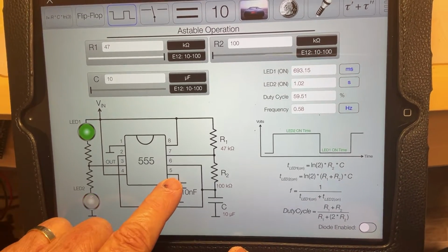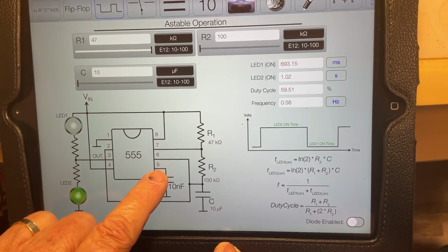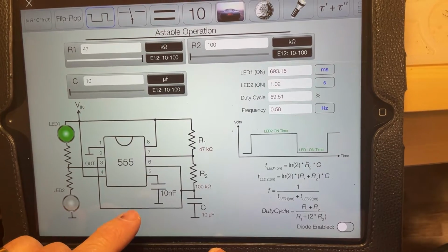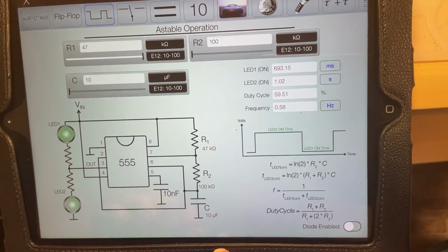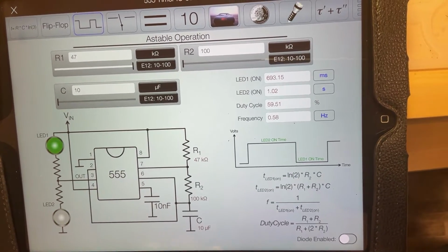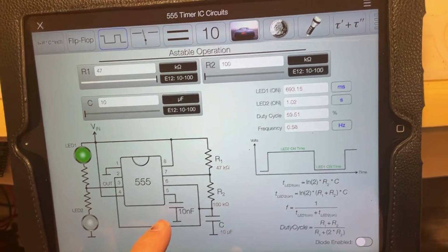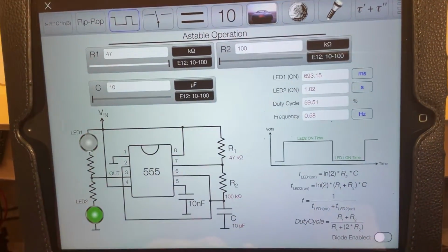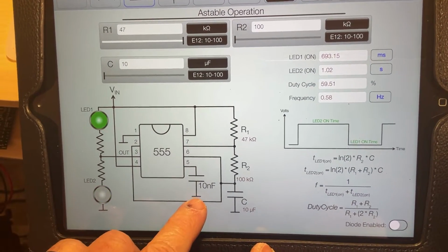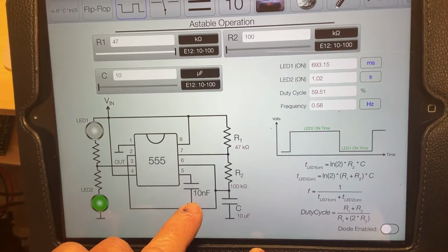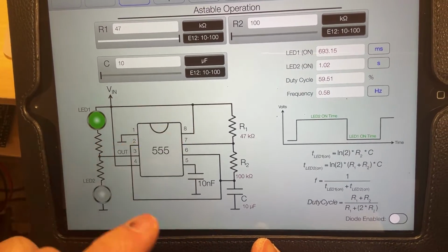If you want to control the oscillator by using pin number 5, you build the circuit called a voltage controlled oscillator, VCO. In the description of the video, I'm going to give you the address of a site of my friend Don Wilcher, where you can see an experiment made with the VCO. At this point, we don't need the voltage control, so we connect it to the ground, decoupled through a capacitor. So we now know pins 1, 3, 4, 5, and 8.